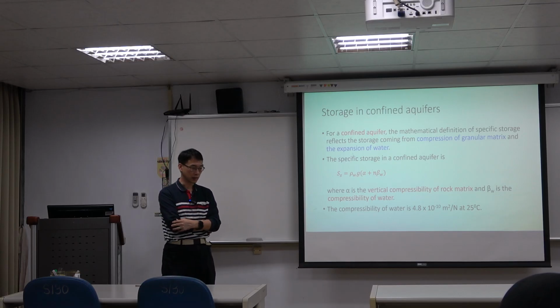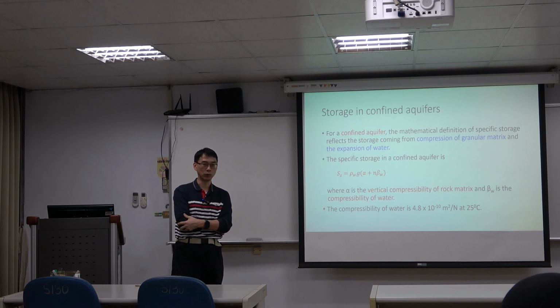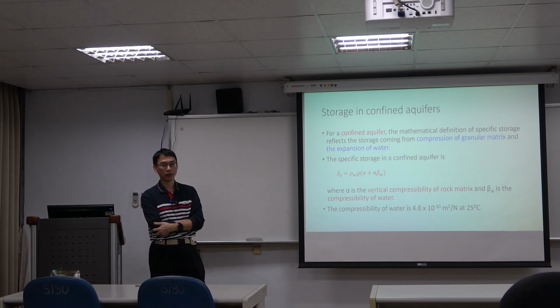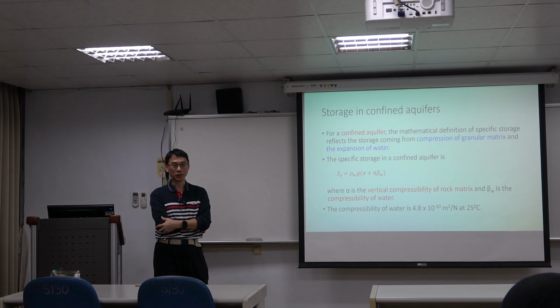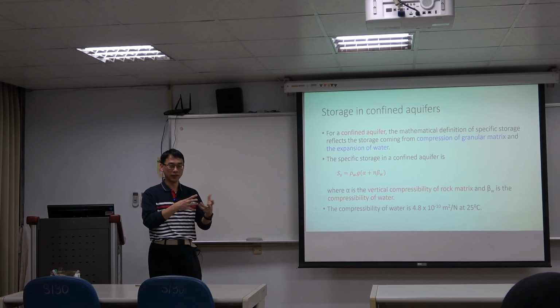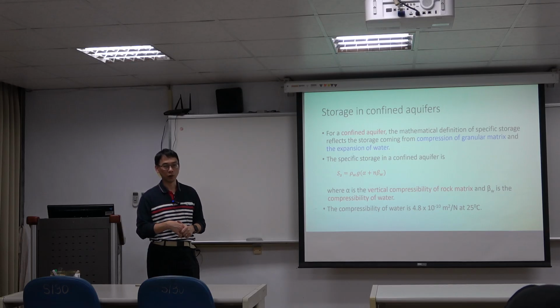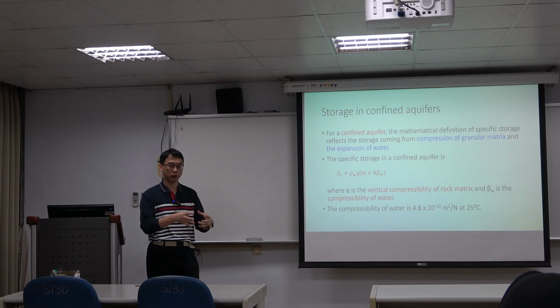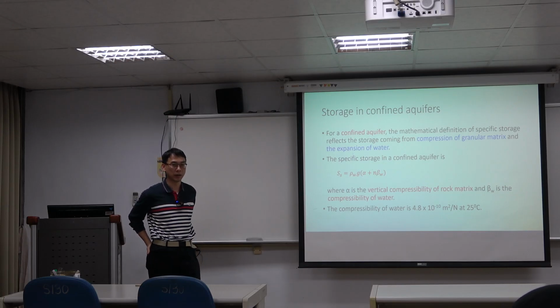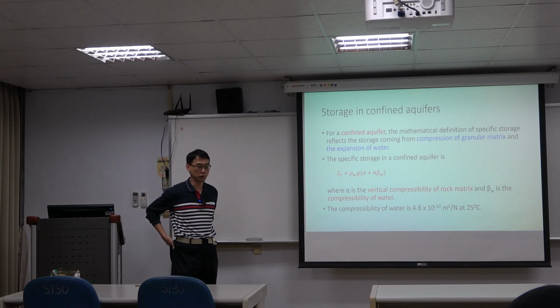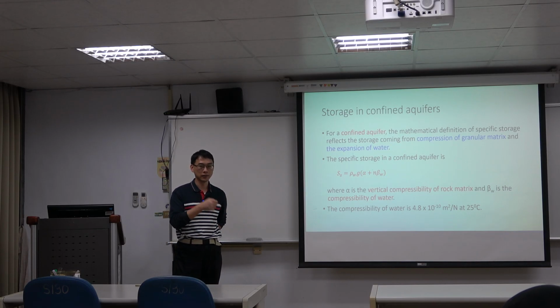And as I mentioned, for the K value commonly, if they are within one order of magnitude difference, we will say they are similar. So even if the sample expands a little bit, maybe the quantity is not largely affected. They're affected, but maybe not so much. Or you can apply a constraint, using confining pressures to let them go back to the original loading conditions. That could be another possibility. But you need to use a triaxial test. Yeah, that will be much more complex for this issue.